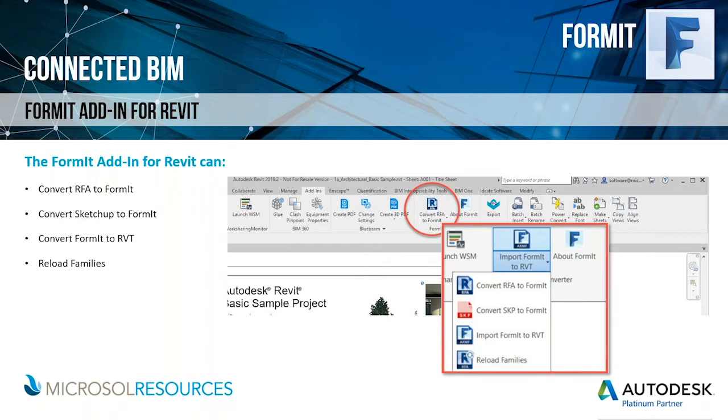but with the converter that is built into Revit, it's actually a faster process now. So again, as I mentioned, the two most common ways to import SketchUp into Revit were either by importing an IFC file or using create in-place family in Revit and then using the import CAD command. However, as we've discussed, there are limitations to how Revit treats this data. Now what we can do is use the add-in through Revit to make the conversion process much easier and faster.